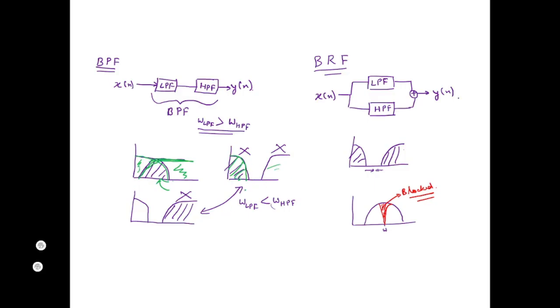Similarly over here, if you apply this high pass filter, this is selected, and when you apply it, no frequency band is available. Here, first we apply the low pass filter, these are selected, and when we apply the HPF, there are no frequency components available in the high pass region. So this is also rejected, and this is also rejected. We will have nothing.